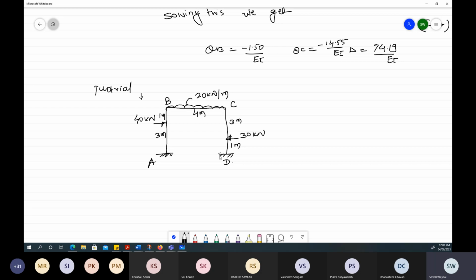Okay. So we have already completed the entire topic of the varieties of problems that come under slope and deflection. Related to this, if asked in the objective exam, what will be asked? First, it will be asked to find the degree of kinematic indeterminacy. Later, it will be asked that to have theta B equal to 1, what will be its unit positive rotation, or what is the stiffness of B: 4EI by L, 2EI by L, or this.